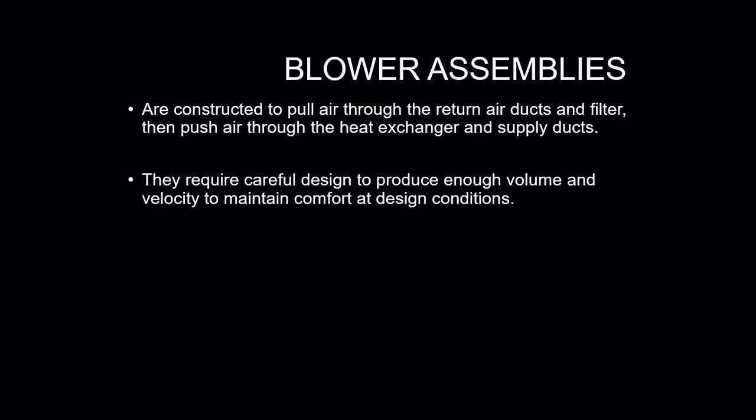Usually these types of assemblies are going to be constructed to pull air through the return air duct and filter, and then push it through the heat exchanger. And if we have air conditioning on that piece of equipment, it's also going to go through the evaporator and into the supply duct. So they are required, and they do require careful design to produce enough volume and velocity to maintain the comfort at the designed conditions.